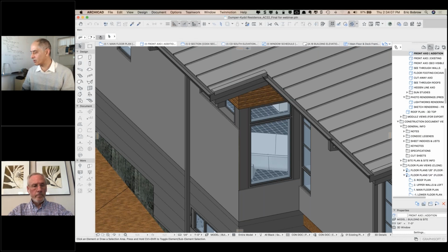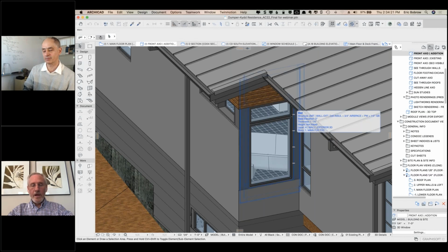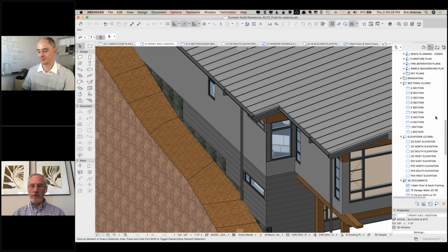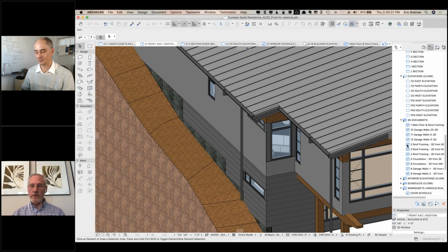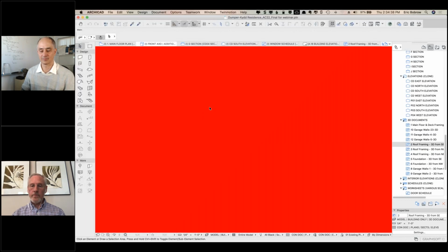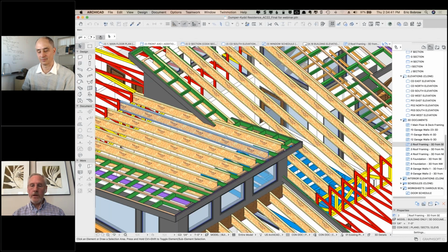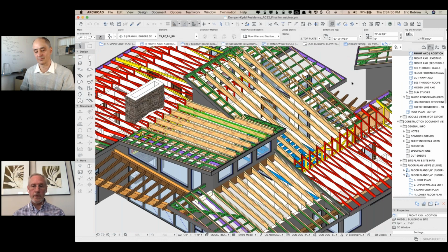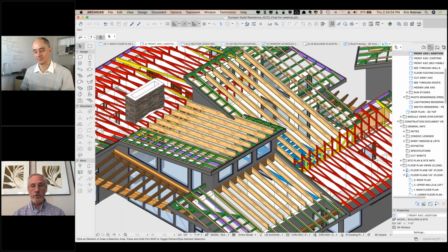All right, and Chris Dvorak, nice to have you there. So I missed a little of the explanation, but how does Mr. Hoffman place the structural members? I've used the rafter add-on, but it doesn't always set them in the most logical way. So are you doing them one by one and repeating? Yes, I do them by hand. It's not that much work once you get one placed and you copy them across, and then you have to do some adjustments if there are holes for stairwells and that sort of thing, adding double ones where you need to. It may or may not have been necessary in some of these places, but the trouble with this one is if I started to model a roof, then I really had to do everything to make it look like it had actually been thought out. So once you start down that road, you really do have to keep going.